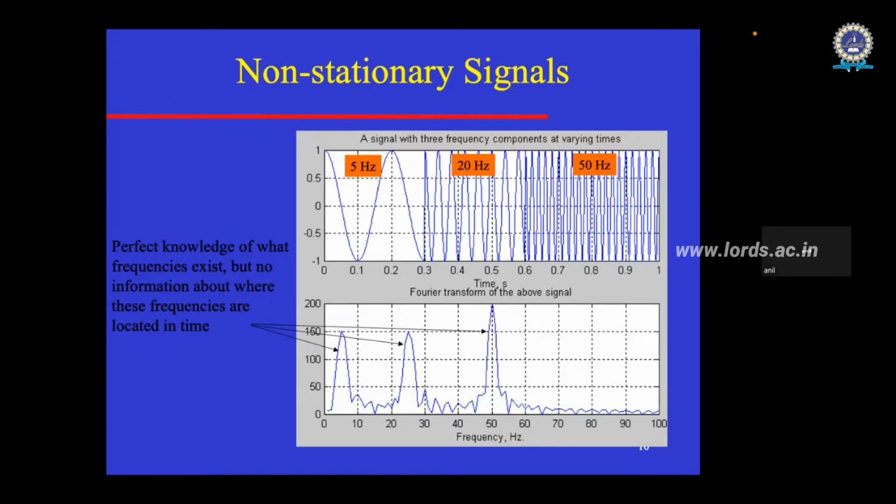This is a time-frequency analysis. In that, for example, this is the time information, time versus sample. This is the frequency information, frequency versus time. There is no ambiguity here. If you compute the Fourier transform, or anybody computes it, it will come like this only. But this joint time-frequency analysis is not unique. I can represent this signal in time-frequency analysis in many ways.